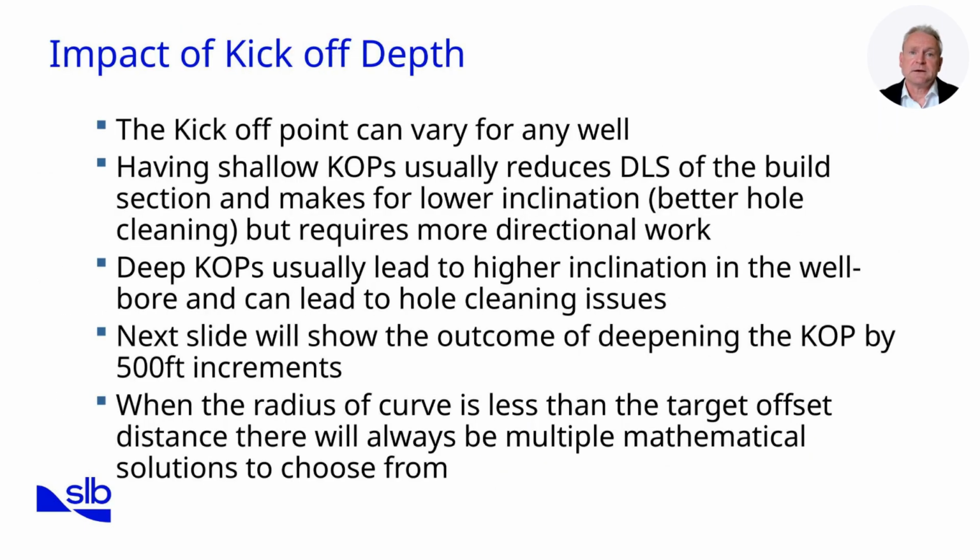The kickoff point, KOP, is the measured depth where the well begins to deviate from vertical. Its selection has a profound impact on the well profile. Shallow kickoff points generally reduce dogleg severity in the build section, allow for better hole cleaning, and support long lateral displacements, making them common in extended reach drilling, ERD. However, they require more directional control.